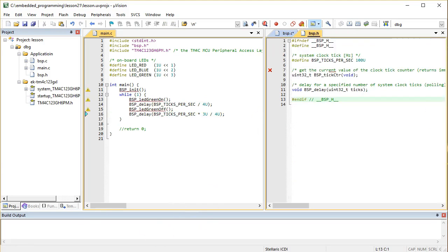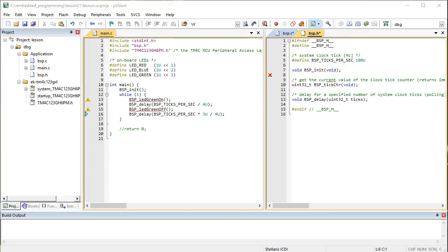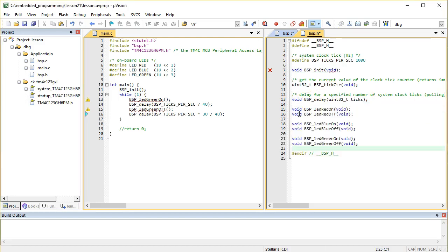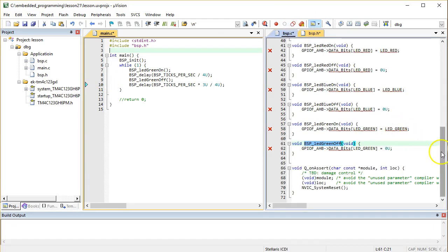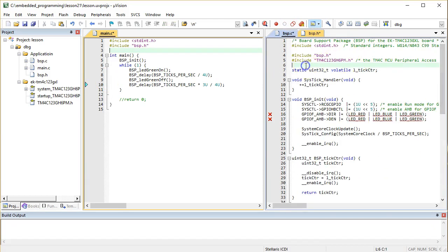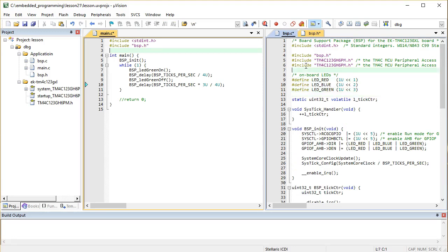Of course, you need to add the prototypes of all the new BSP functions to the BSP header file. And finally, notice that now you can remove all board-specific stuff from the main code, such as the MCU header file, the LED pin numbers, etc. You can move all this stuff into bsp.c because your background loop no longer depends on any of these details.